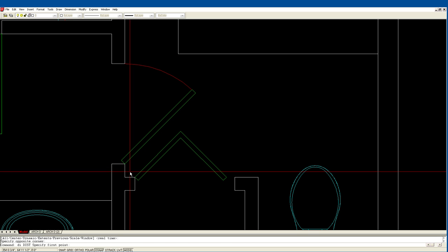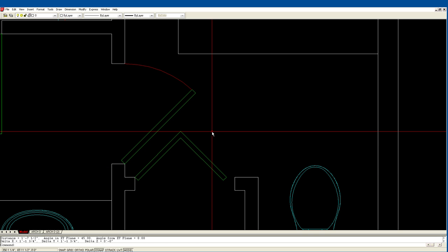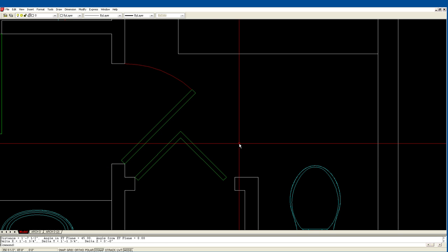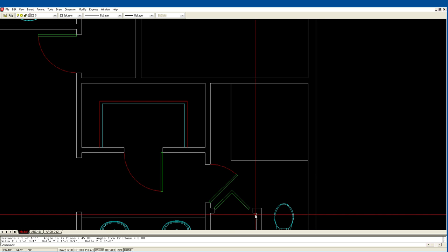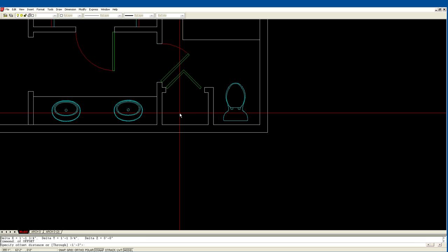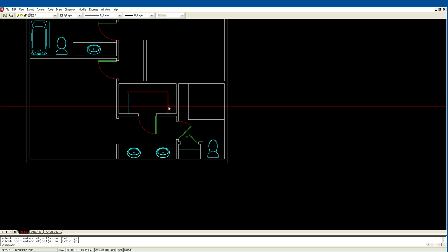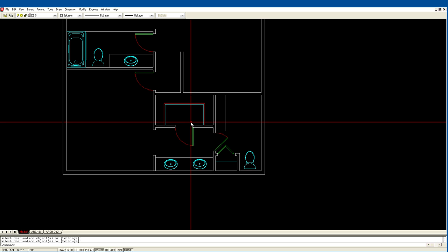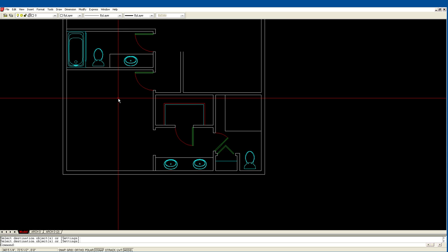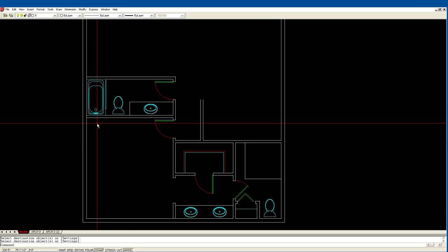The distance here needs to be half, which is 18 inches, 1 foot 7.5. So that is a 36-inch. Here, we're just going to offset 16 inches again, and we're going to match properties to something on the utility layer. We're not going to put the dotted line for clothes hanging because that's a linen closet. So we have our walk-in closet. We've got a good sized master bedroom.